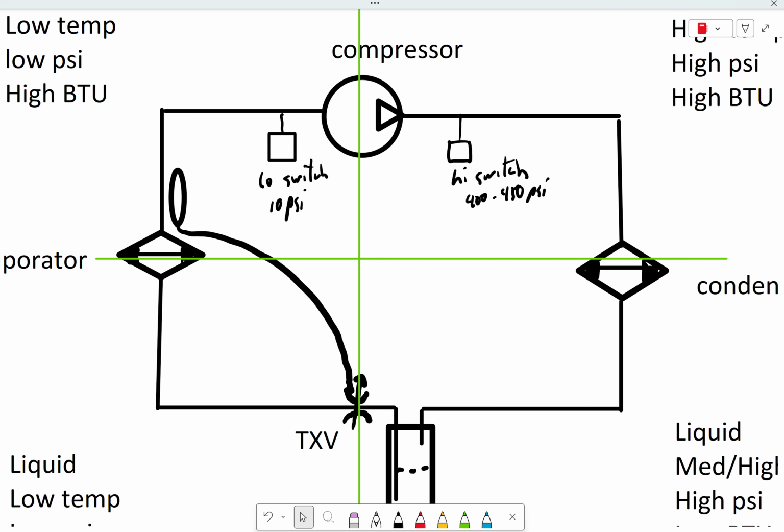So what that tells us is if the pressure gets low because the temperature is low, let's say that refrigeration system is sitting in a machine in the middle of winter, if you turn the compressor on and there's no refrigerant moving in the system because there's no vapor in the system, that's not good for the compressor. Do we know why? Because the compressor is lubricated by the oil that's being carried around with the refrigerant, right? Just like a two-stroke gas engine. So yeah, you're going to destroy your compressor because there's no lubricant.